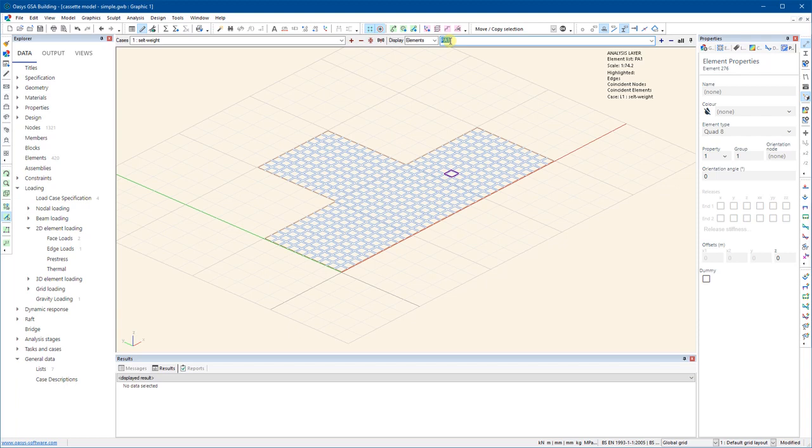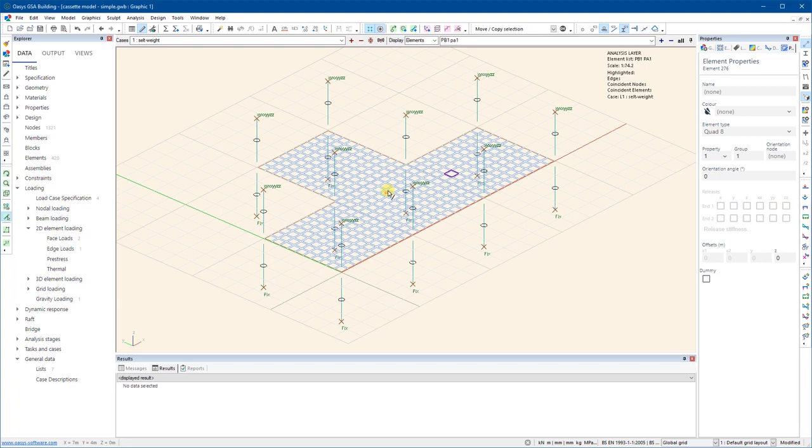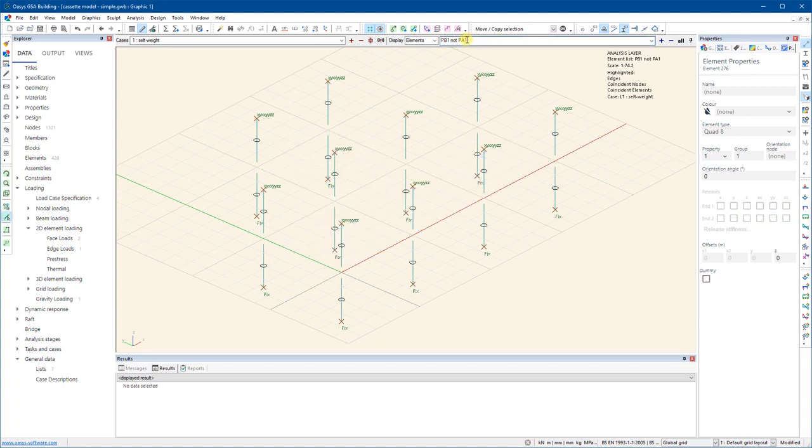For stick elements, 1D elements, they're beam elements, so that would be property beam 1. And all my columns have exactly the same property. I could go PB1, PA1, and that shows me everything. So it gives you a lot of flexibility. So you can say something or type something like that. You can do not PB1, not PA1. So again, if you look in the manual in the help, it again helps you out with the syntax for all of that.